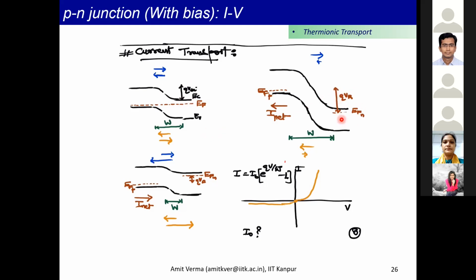Like in this case, if there were heavy doping on two sides, you make what's called a Zener diode. In that case, when you apply a reverse bias, what can happen is you can have direct tunneling of electrons from conduction band to valence band or valence band to conduction band. So most of the devices we work with actually work on this thermionic principle in which electrons go over the barriers. And all these devices, be it MOSFETs, BJTs, Schottky diodes, PN junctions, they all operate on this principle.